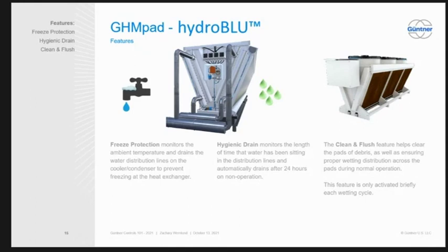Yeah. Well, I think the water in Chicago is probably going to be some of the best in the nation. But that's a different subject. As far as water and water scale, it's normal city water, so it's going to have that. These pads are not designed, they're not like a coil, they're not designed to be there for life. They are consumable parts. Every one of the adiabatic pads, and it really depends on the water quality.